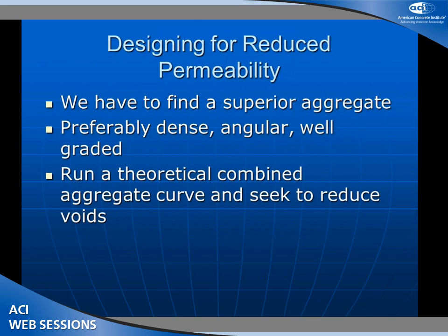So we know we want to maximize our aggregate volume, minimizing our paste content. So we definitely want to use a superior aggregate, not pit run stuff. This one's going to take some substantial quality control on the producer's end. Down south, we have a lot of mom and pops. So for most of the projects down there that we get into this, we're going to buy from the major producers. Those are the better quality control programs.